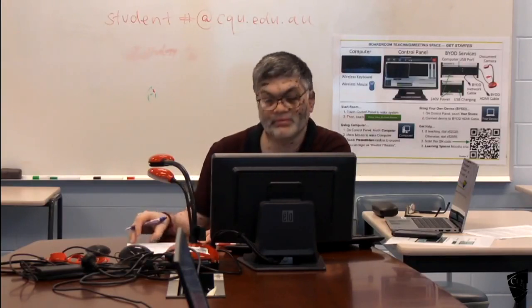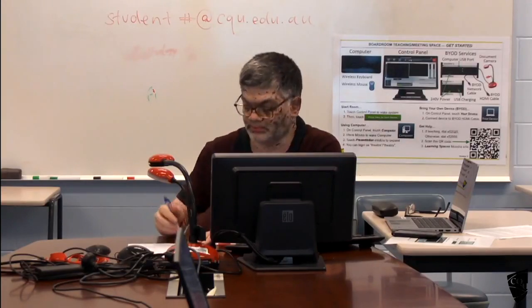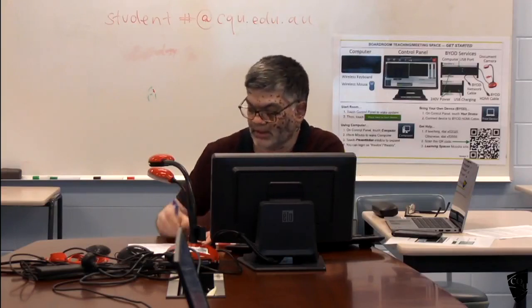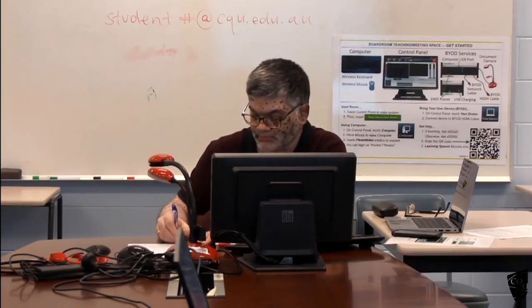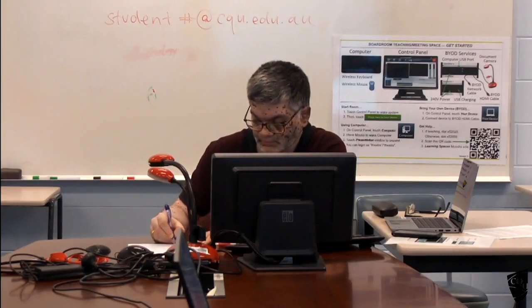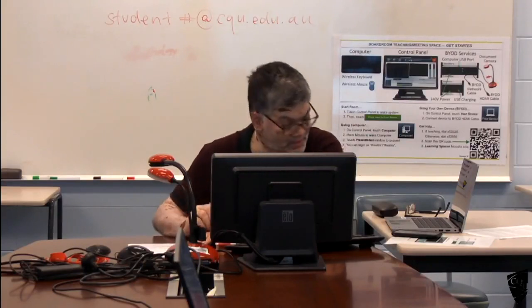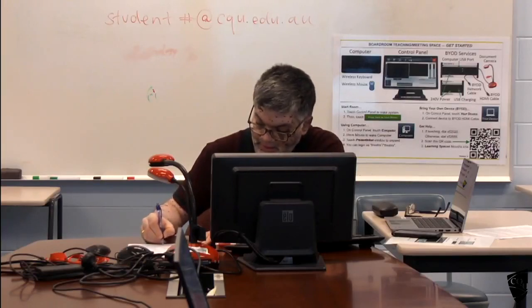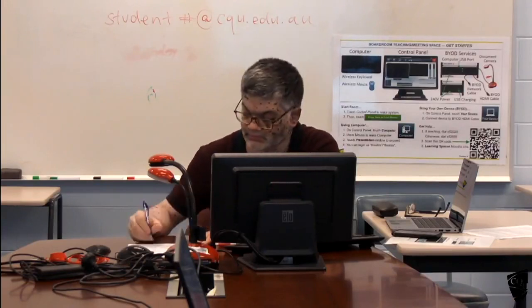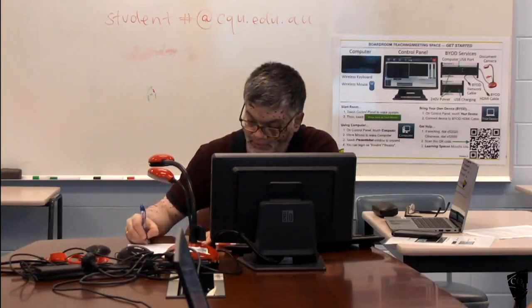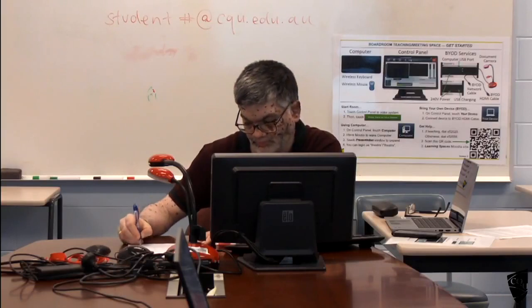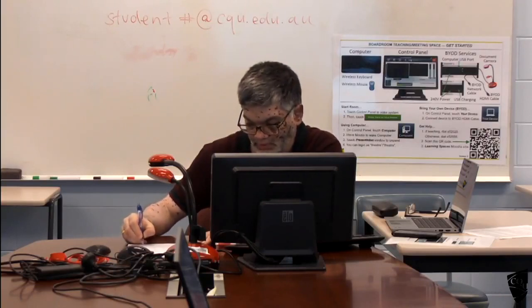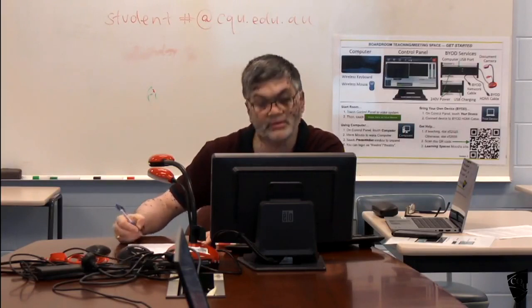At support, we will provide reinforcement on the top and find the maximum moment, then find AST and check for minimum reinforcement.